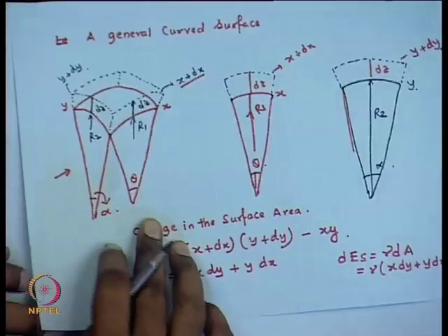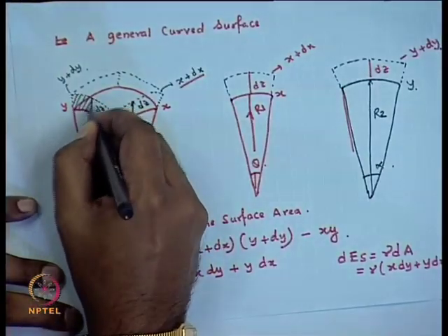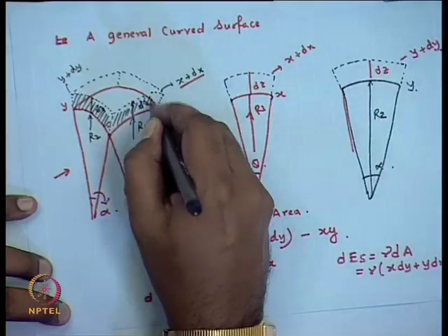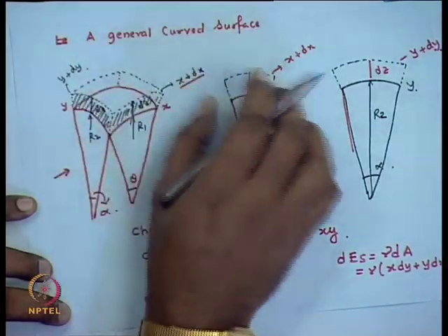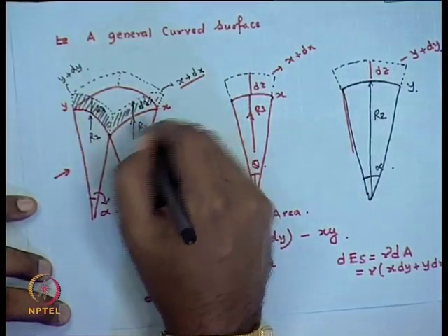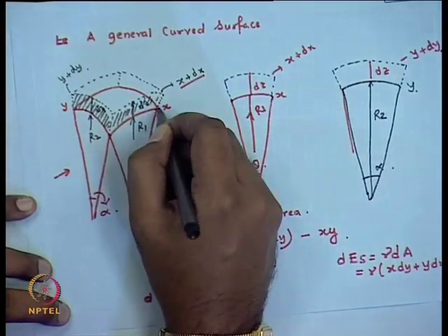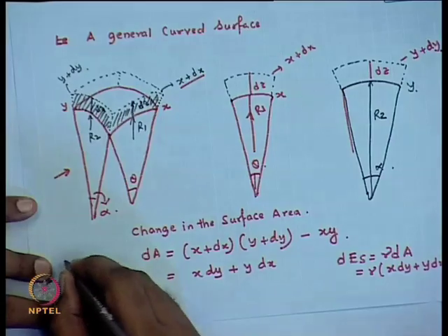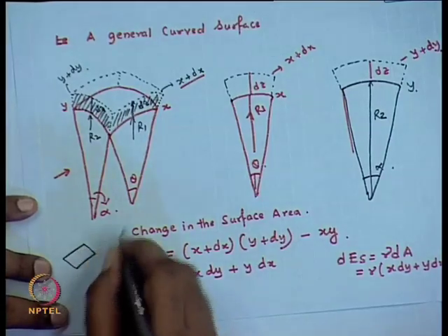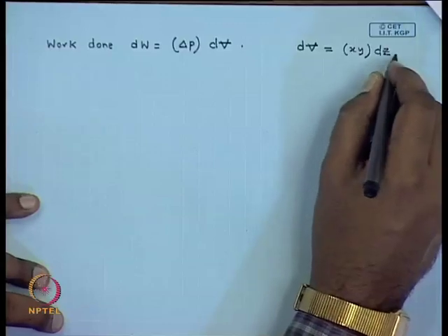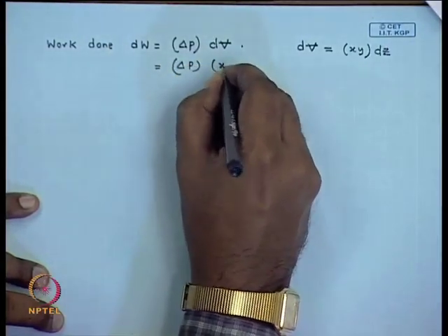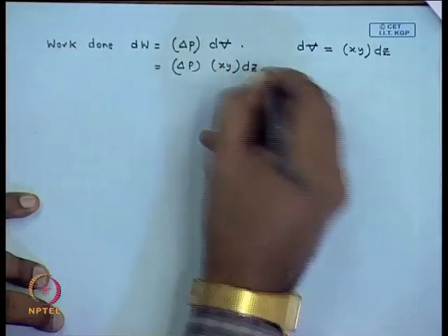So, this is the change in the volume you have achieved over here. So, it is x y into delta z. Of course, we are assuming that the curvature at this particular point is negligible. So, therefore, the surface area is x y. Ideally, that would have been the case had the surface been flat, but we are doing that approximation, it is perfectly fine. So, you have delta p times x y into dz.